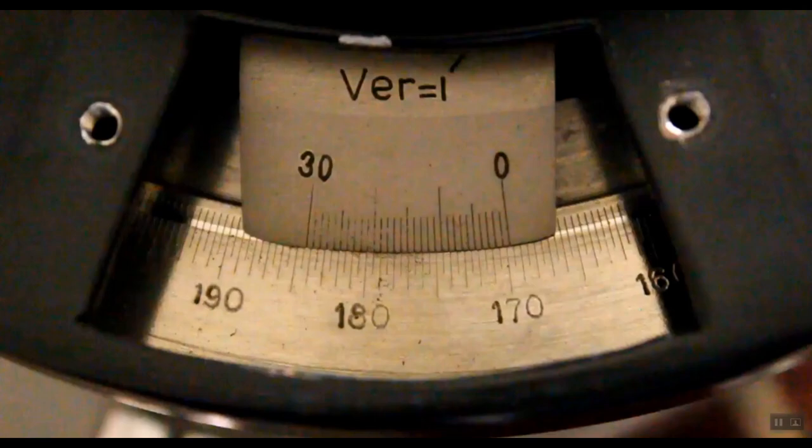This shows another sample reading. Here the zero of this vernier scale actually lies in between 169 degree 30 minutes and 170 degree. So we have to take the minimum value, that is 169 degree 30 minutes. Then find out which line exactly coincides with any line of the main scale. That actually gives you the vernier scale reading. And then MSR plus VSR into LC will give you the total reading.